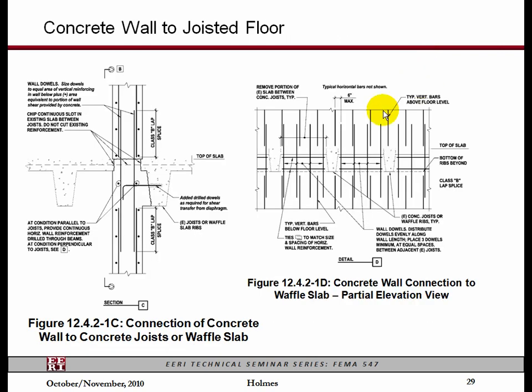Again, as I mentioned, you often might want to put your shear wall location not on a grid line or not on a joist line, because if you put it alongside in a joisted floor, you can come up with a detail like this where you can get a good connection into the diaphragm by drilling into the beams or the joists.